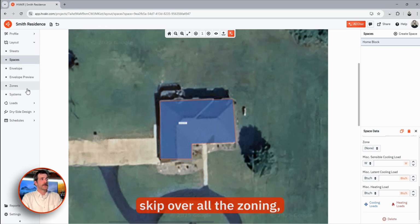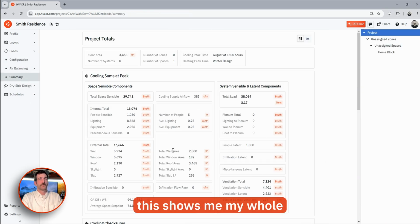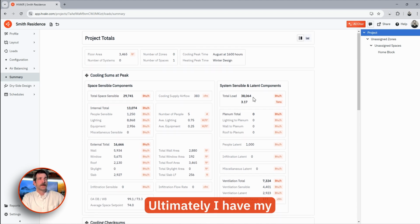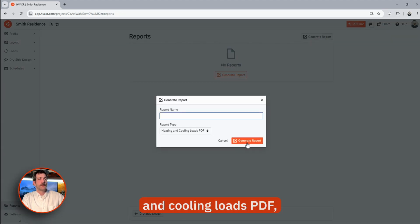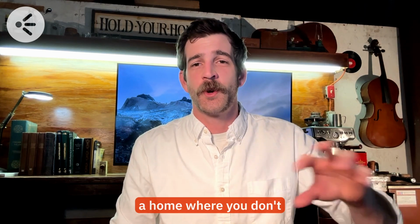From there, I can actually skip over all the zoning. I can go to loads, summary. This shows me my whole project, so this is fine. And this is going to give me all that data. Ultimately, I have my total load over here, 3.17 tons. This can be printed as a report using the reports feature here. Generate my heating and cooling loads PDF. You hit generate, and that will download your report. That's one application. Very quick block load for a home where you don't have a set of plans.